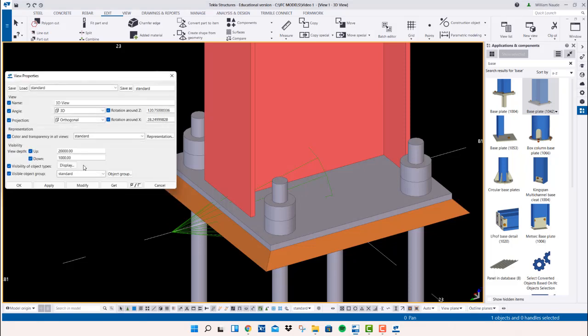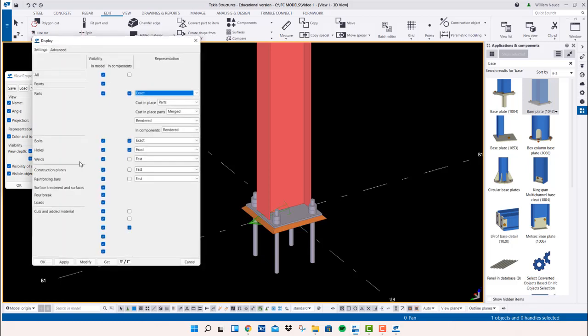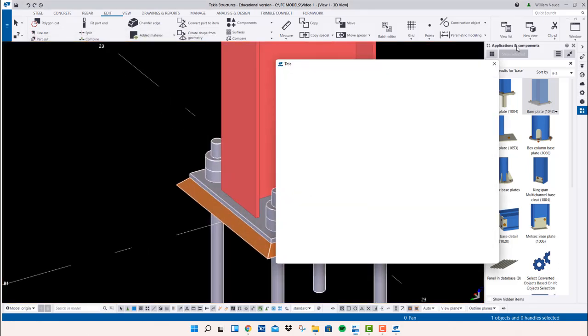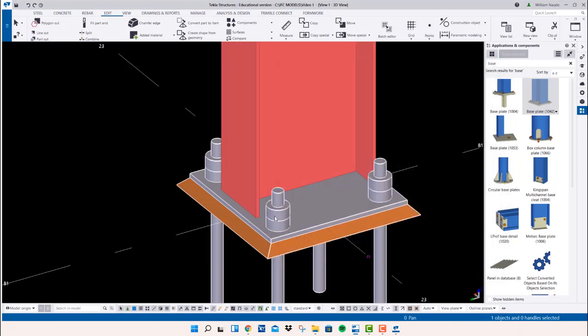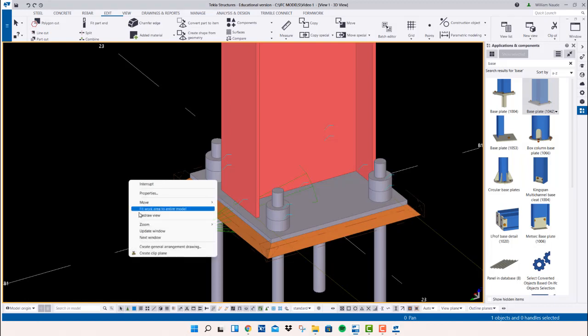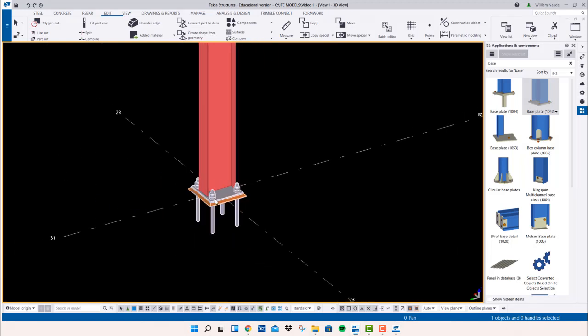The first way, if you want to be able to still edit it, click on the background, choose display, and you turn off component symbols and you modify it, and you'll see that it's now gone. But if you wanted it to reappear, you have one of two ways. You can either just delete, Control Z to undo, and it will reappear, or you can just go back to the settings that you've just set and do what you want to do there.